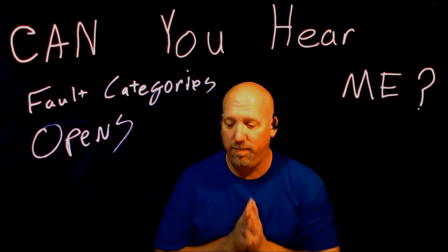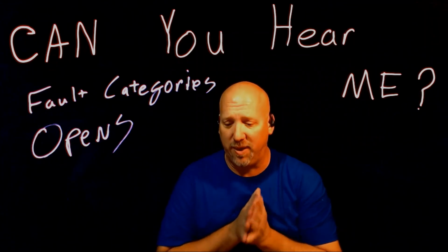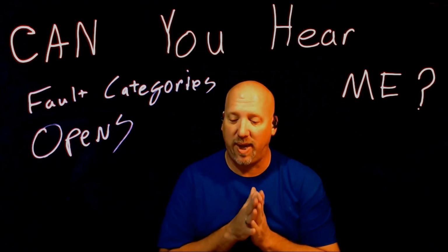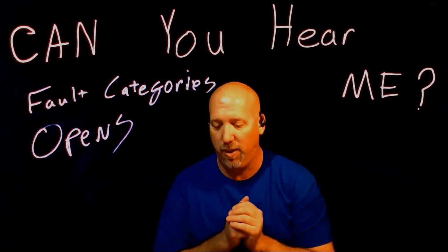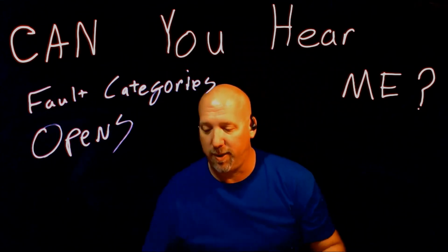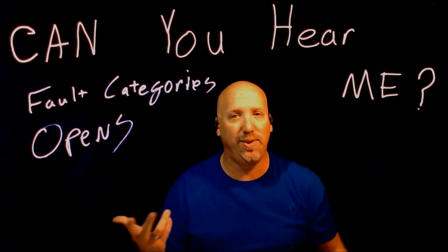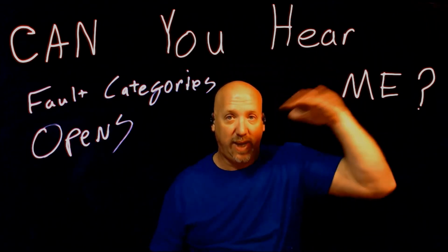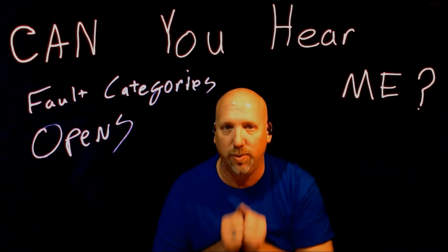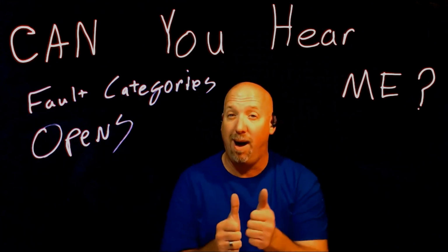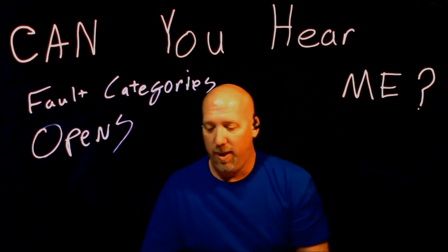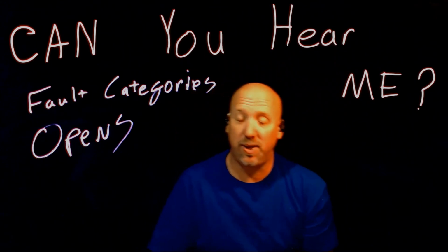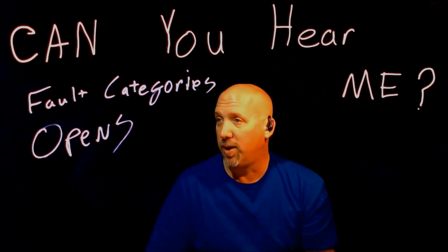Opens are very common. The diagnostic process is very different than shorts because you'll often have a scan tool communication issue with other modules. If so, many modules probably will have a U, a B, or P code, one of whichever modules are communicating there. You can use a scan tool health check. Sometimes you do that health check, and it scans all the modules. It's a great tool to have. If your scan tool does that, awesome. That is so great. All codes or whatever it's called there, to see which modules have communication codes stored, and which ones are not currently online there.